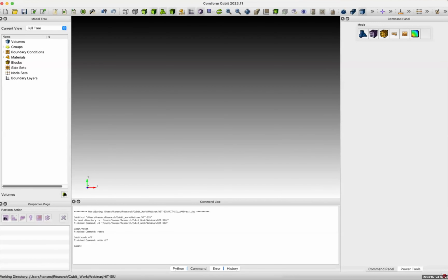A lot of times I'll do things in the GUI, but I want to save out the commands to a journal file. This is so I have something repeatable, so I can get back to the state I was in if I make a mistake. Sometimes, undoing in these complicated models is just not so efficient. So I'm going to do a combination in these examples of the GUI, and also executing some journal commands, which I will try and show.